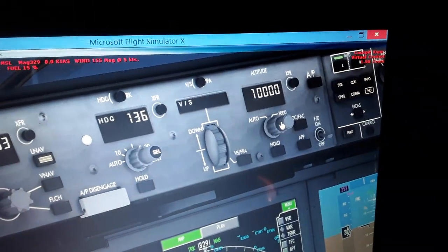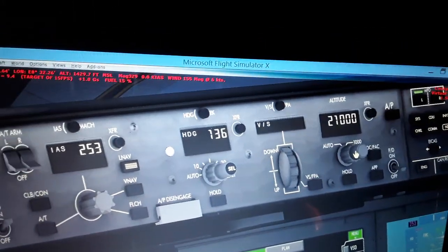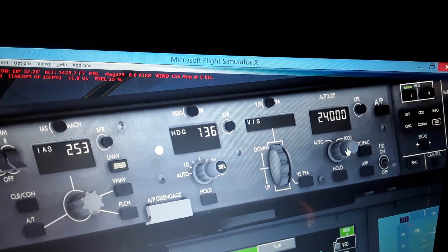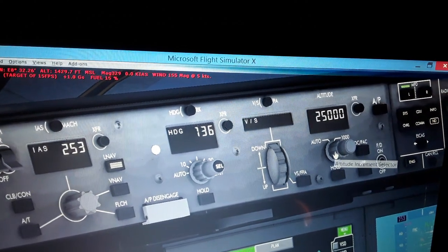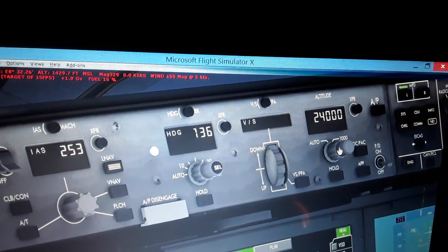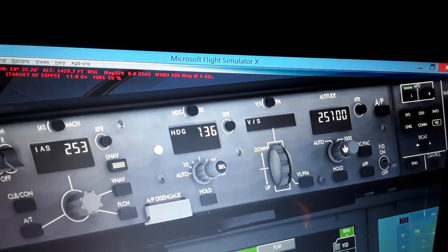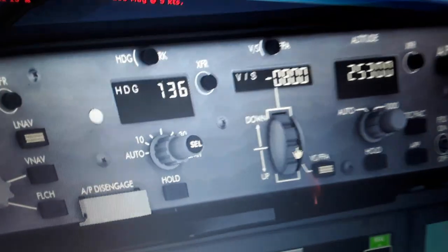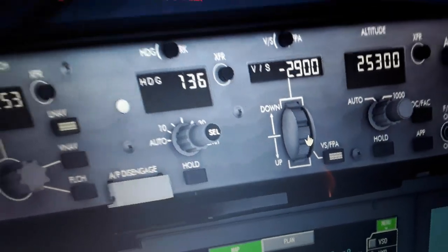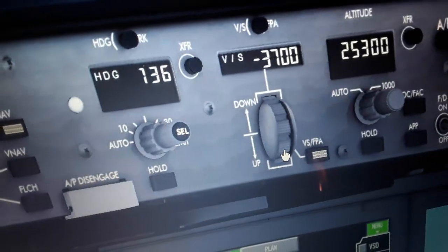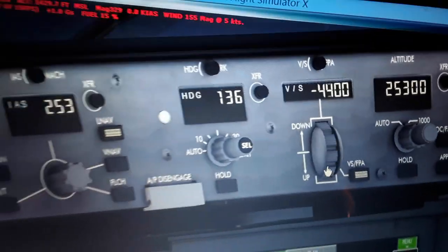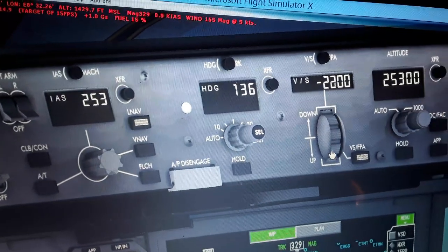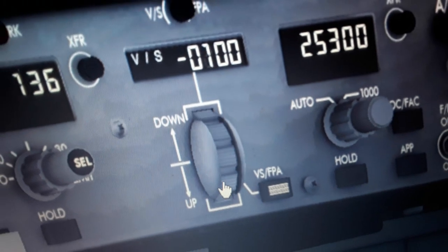The altitude we're gonna be flying, 35,300. Select thousands, then hundreds. Vertical speed, we can zero, we can descend like this, or we can climb the other way when we reach. So you see all the controls of the autopilot flight director system panel.